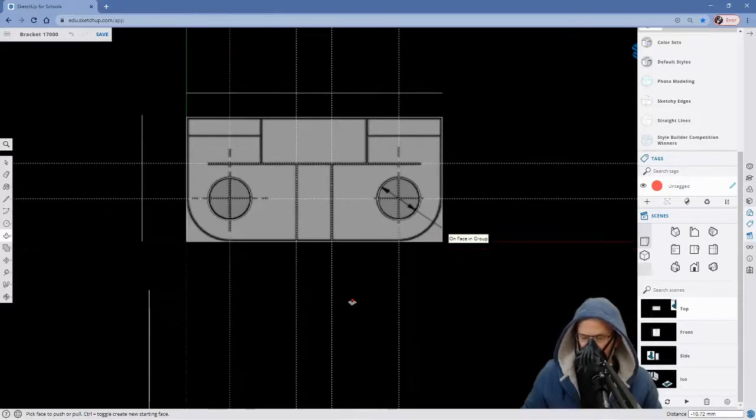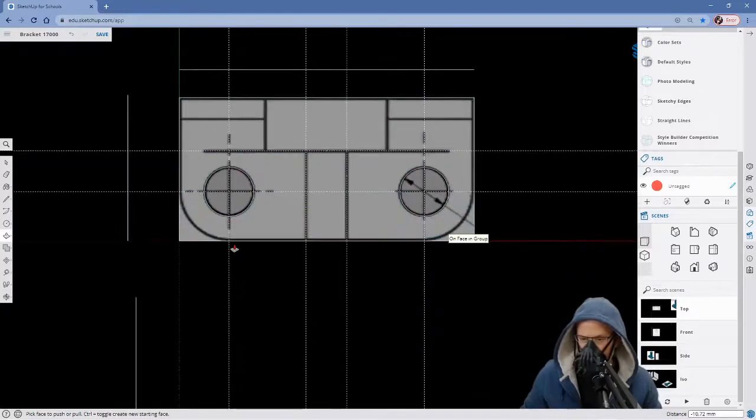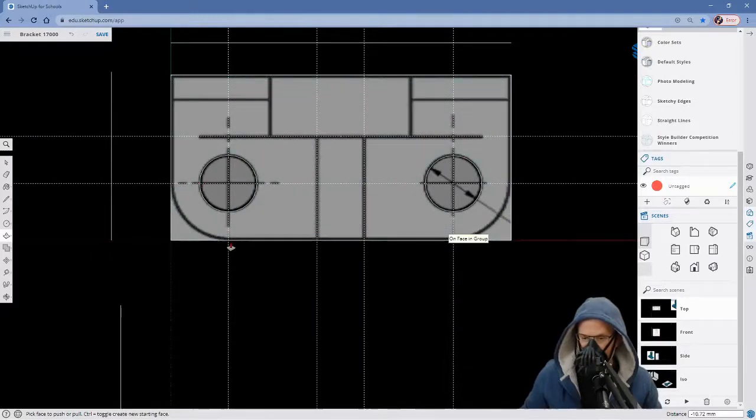That's good. All right, I think we need to try to create this sweeping corner here. What I'm thinking is that I have the guidelines in place. What if I were to use the arc tool to try to create this sweeping motion? Let's see, I will use the arc tool, intersection, intersection. Oh, and it's tangent to the edge. So I will click. The tangent is purple.